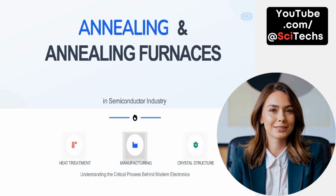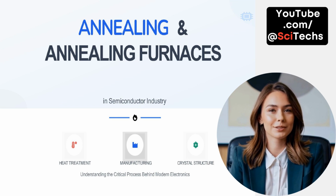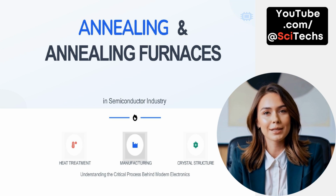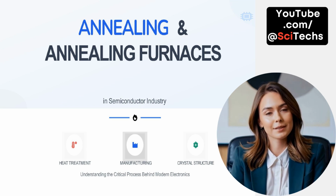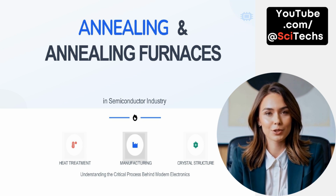structure. As a heat treatment, it is used to repair damage in the silicon lattice caused by ion implantation and to activate dopants, ensuring electrical functionality. In terms of manufacturing, annealing enhances performance characteristics like carrier mobility and junction depth, supporting the production of high-performance transistors and integrated circuits. Lastly, annealing helps manage the crystal structure by relieving internal stresses and restoring order in the atomic lattice, which is essential for maintaining material integrity and electrical properties.